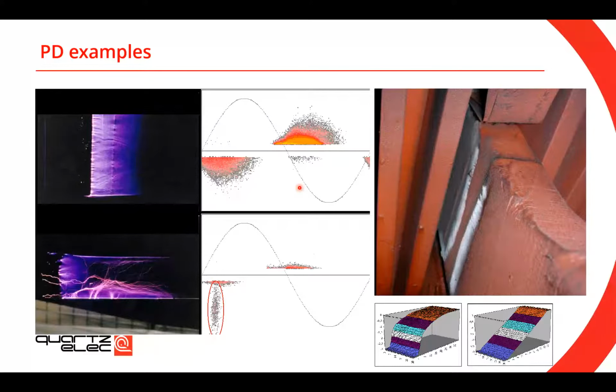Now, focus for a minute on that big picture. What you see here is the slot exit and the stator bar coming out of the core. In that location, you have that overlap from the semiconductive paint and then the stress grading paint. This stress grading paint, you can see on the left-hand side, is there to make sure that the potential level comes from high voltage to zero in a controlled manner.